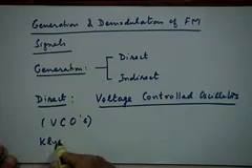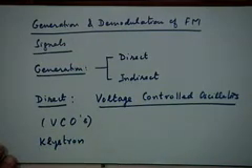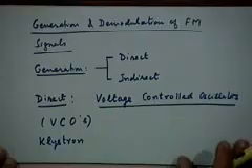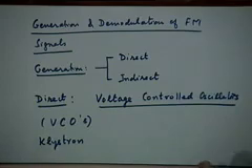If you have come across astable multivibrators, they are nothing but voltage control oscillators, right? If you are working with microwave frequencies, there are special devices like klystron, which can be used as voltage control oscillators, and so on and so forth. Since it depends on what frequency you are working with, you have different kinds of devices. I will not go into a very detailed discussion of the design of the voltage control oscillators, except to say that it is possible to design circuits, devices, systems which can be essentially voltage control oscillators.